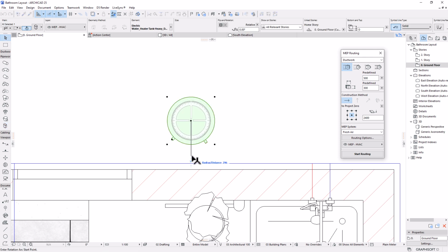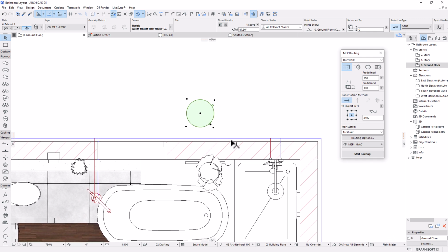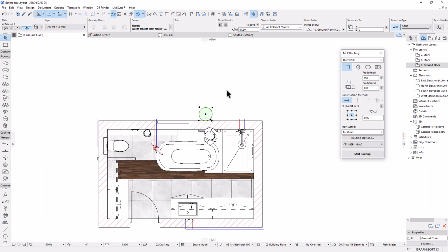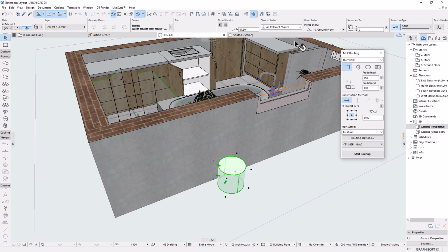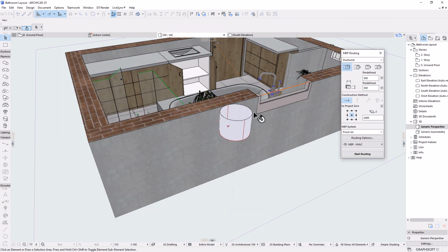I'm going to pick it from the center and then rotate it along to this direction. I'm very interested in these points because they're the ones supposed to connect to the whole system. So I'm going to Control D again on your keyboard to drag it right on the edge of the wall. It's going to be wall mounted. So if we check on 3D, boom, this is what we have. Let's select it and then set it up around 980 to this height. This elevation is good.